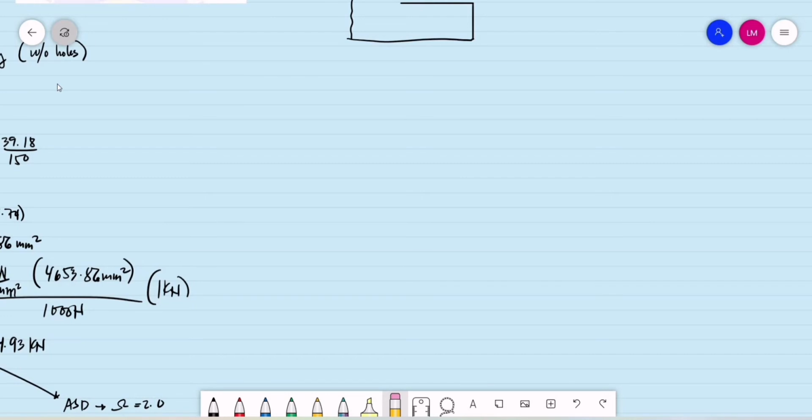But before we proceed to the block shear strength, let us first clarify that in the analysis of gross section yielding and tensile rupture strength, our assumption is that the failure will occur in our tension member, that is on the given angle.